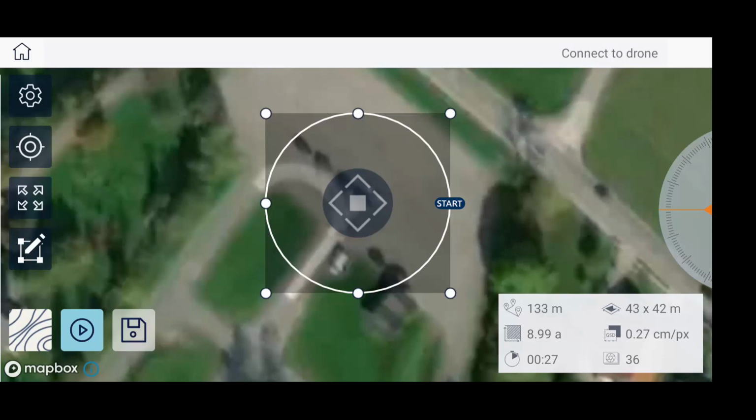in 3D Survey. And then click on play, wait another minute or two, improve the gimbal position if you need to with the remote controller, rotate the drone a bit with the remote controller stick if you need to, and let's say after 10 minutes you're more or less finished with data acquisition on the field for accurate 3D model generation.